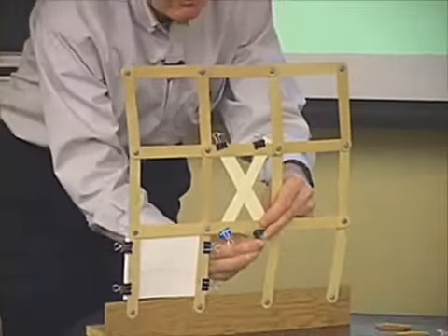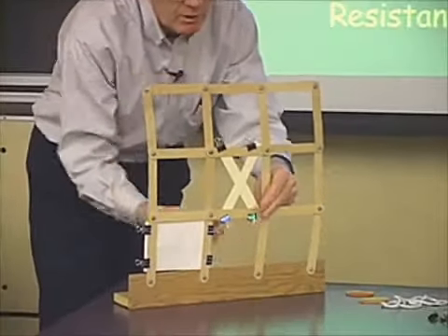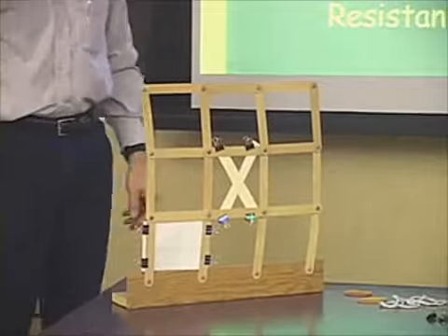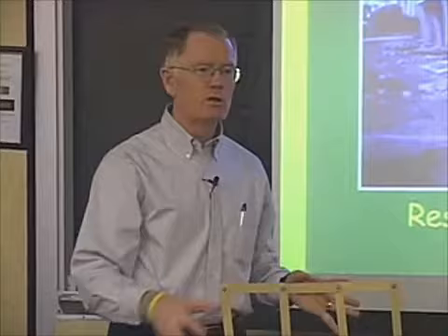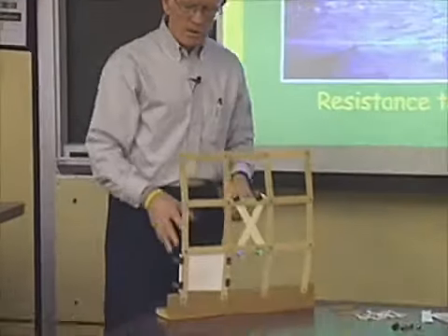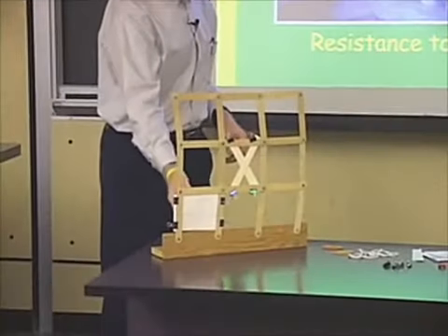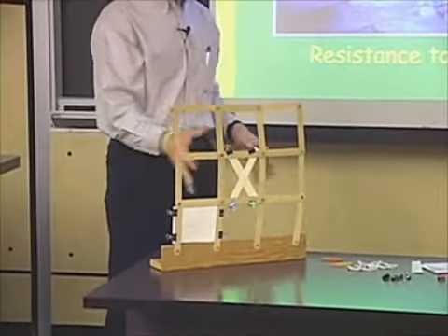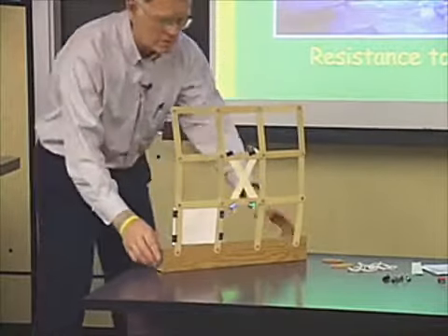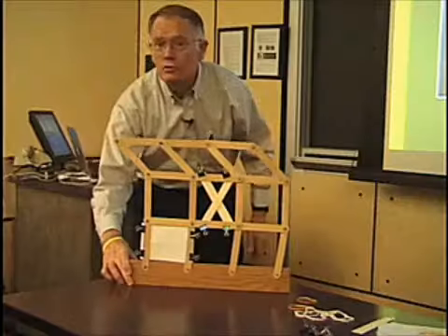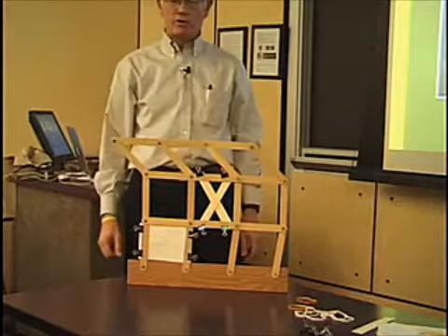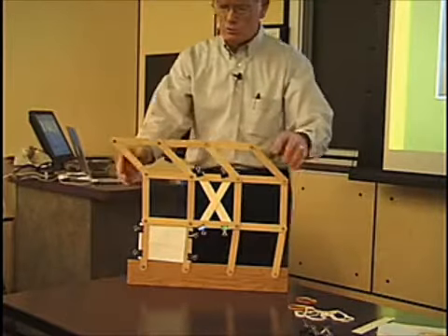And if you drive by construction sites where big office buildings are put together and you see them in the stage where only the framing is visible, you'll often see this kind of configuration. So now we've got a good shear wall, we've got shear strength in the bottom story, we've got cross members here to produce shear strength in the second story. Now earthquake comes along, bottom two stories are shear resistant, they can withstand horizontal motion of the building.